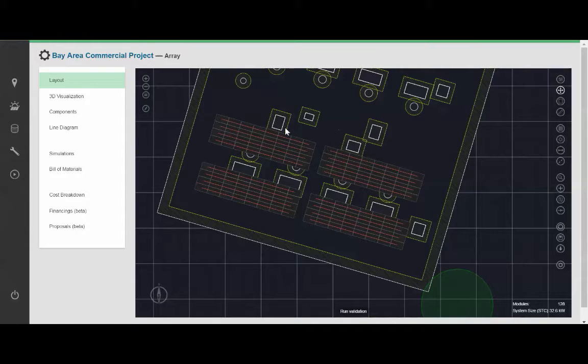It's also possible to drag and stretch additional rows and columns of each block in all 4 directions. Note that it may affect the original string lines, so sometimes it's best to rerun the command again to resize them.